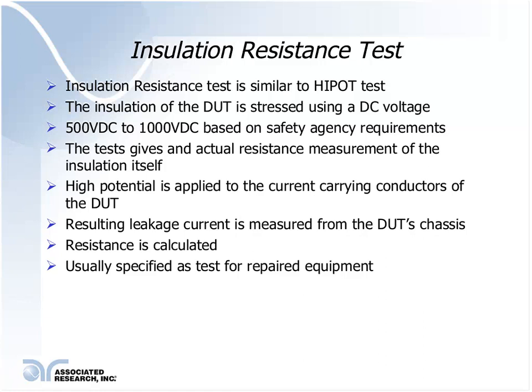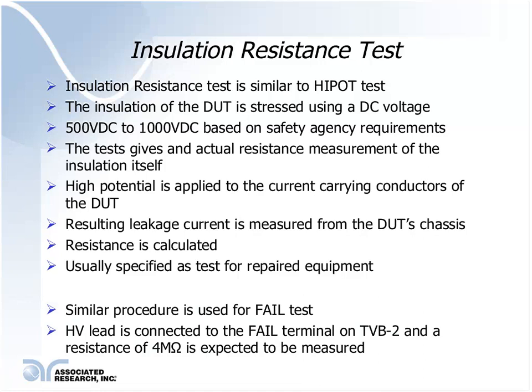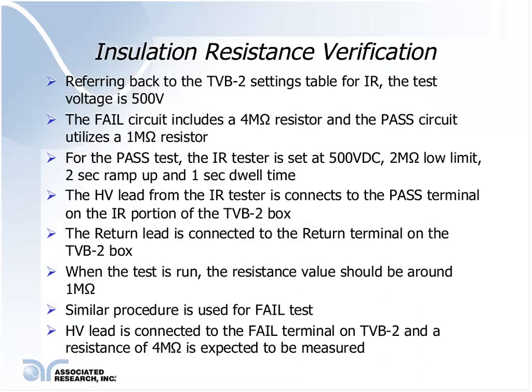So, having refreshed our minds with the insulation resistance test, we're going to get into how the IR test can be verified. So basically, how can we verify if our IR tester is working within specs? Well, similar to the other two, the Hipot test and the ground bond test, we're going to use the same example of our TVB2 box, a verification box, and the table.